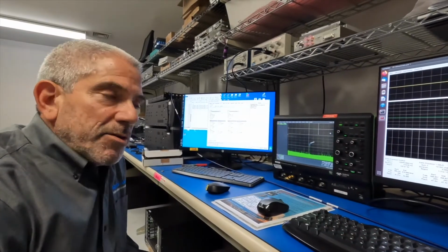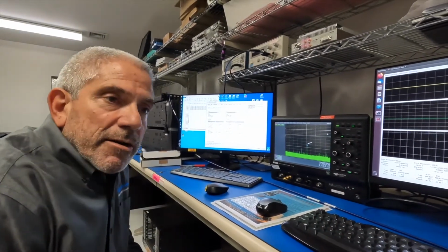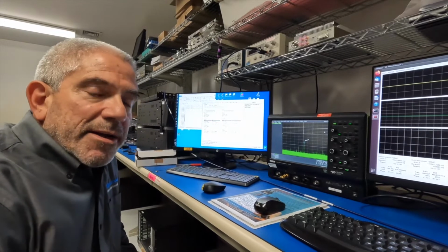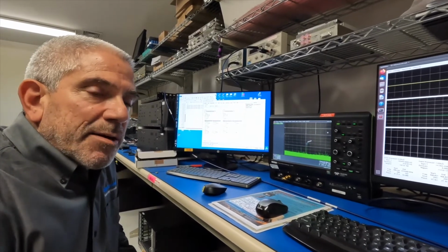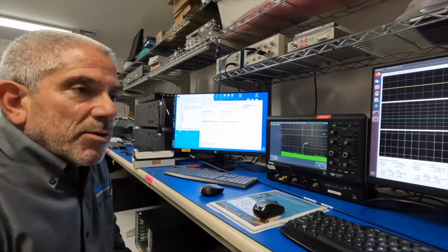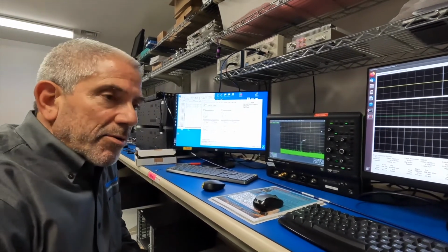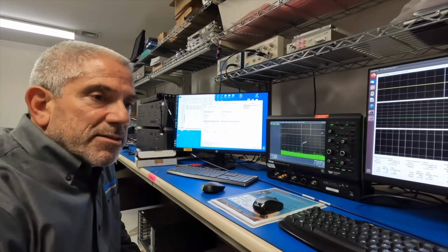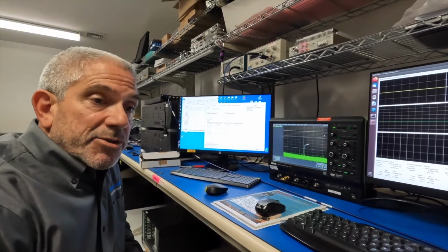Okay, so what we're going to do now is go to the RFPG, the RF playback and generation system, and we'll put in a more complicated pulse. Fixed pulse width and PRI, 25 microsecond pulse width, 100 microsecond PRI, but it has a 250 megahertz linear FM chirp on it.